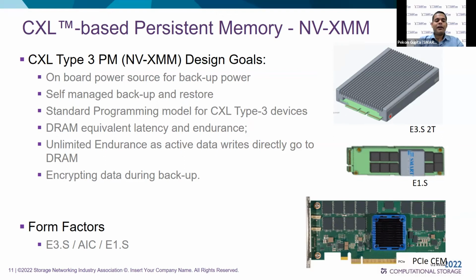memory modules which are connected through a serial interface, because they can be physically removed from the chassis. The EDSFF form factors can be plugged out or hot plugged back into the chassis by an end user. And therefore, the power source, which is used for backing up the data from DRAM to NAND, should be maintained or should be available on the module itself.